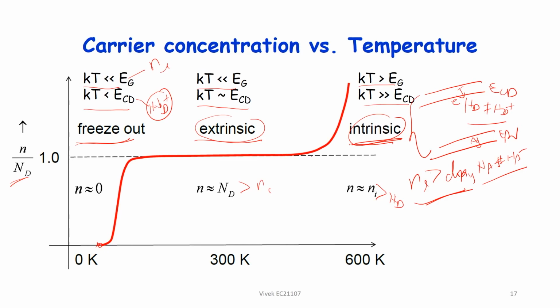So Ni is basically kind of increasing from here like this. So this region is dominated by the dopant. So maybe up to here you can use it, right? Beyond this, doping becomes meaningless. So that means this device will not function as desired, right?